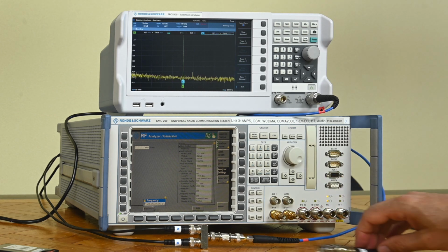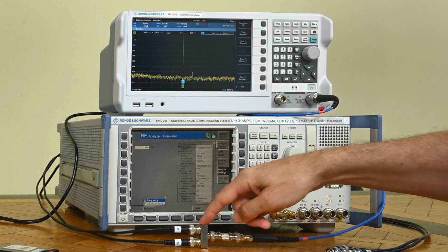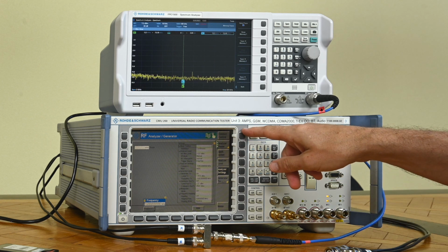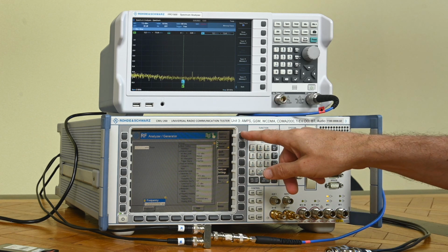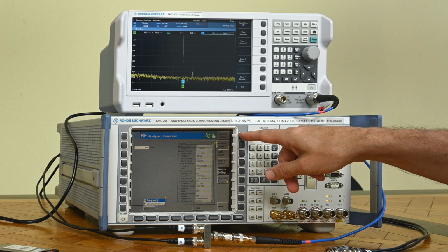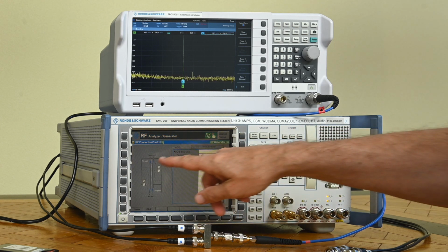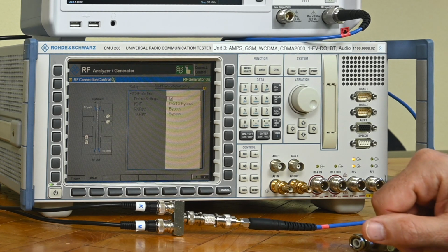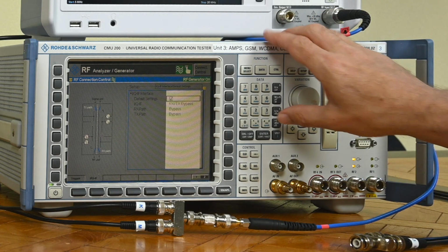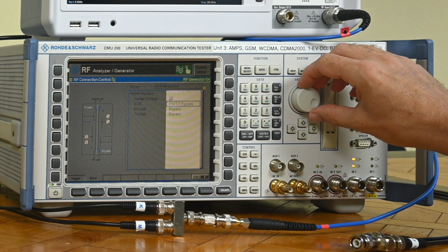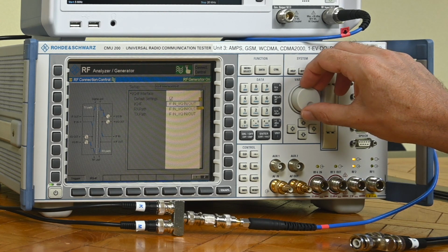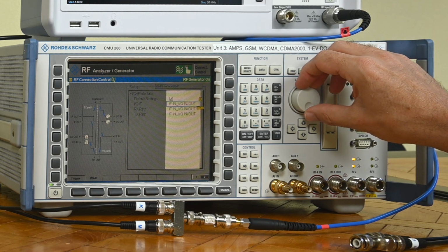Right now, I have my spectrum analyzer connected to the transmit path loop. But right now the unit is not yet in bypass mode. So I go to the control connect. I end up right away here in the IQ menu. What I'm going to choose is, well, we are in bypass mode, but not bypass mode with monitoring. So let me see where it is.